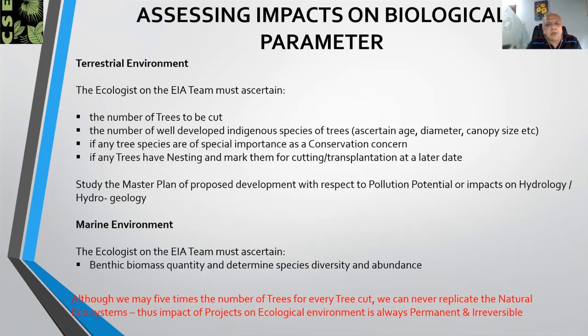The master plan of the area should be well known to the ecologist, and the pollution potential of the project or the impacts due to the project on hydrology, hydrogeology also should be known to him. In case of benthic environment, the ecologist must study the benthic biomass quantity and determine the species diversity and abundance.